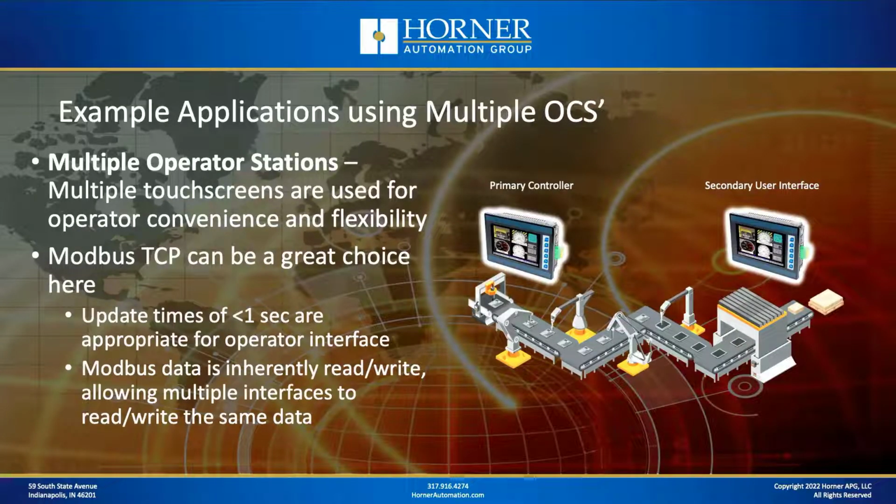Now let's talk about an application where Modbus TCP does typically work well. That is a scenario where you've got a machine or an application and you want to have multiple operator stations. In other words, even though you might have a single controller that's controlling the machine, it would be extremely convenient or even mandatory really to have multiple locations where the machine can be monitored or controlled. So that's the application we're talking about here.